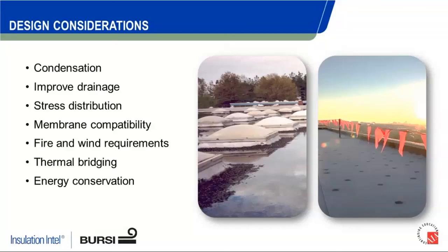And just to give you an example of what thermal bridging looks like in a roofing system, a low-slope roofing system, the picture on the right is actually a roof that has frost on top of it, and you can see the fasteners that are used to hold down the insulation underneath that membrane are acting as thermal bridges and are warming or melting that frost before the rest of the roof. And so it's a real concern with the roofing system and thermal bridging with those fasteners. We'll talk about that in a minute, about what some best practices are to deal with that.